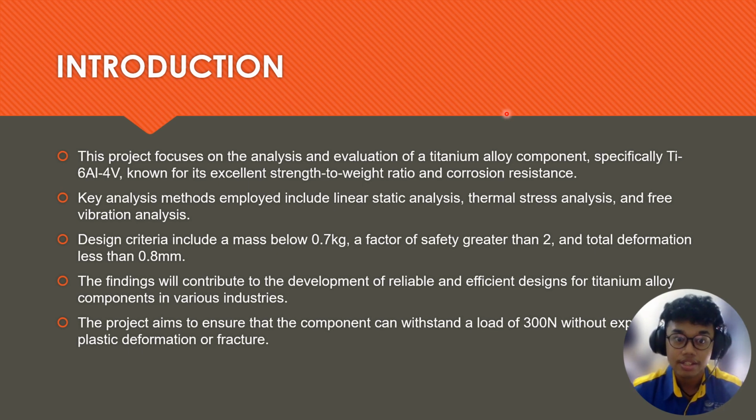The key analysis methods we employ are linear static analysis, thermal stress analysis, and free vibration analysis. The design criteria include a mass below 0.7 kg, a factor of safety greater than 2, and a total deformation less than 0.8 mm.